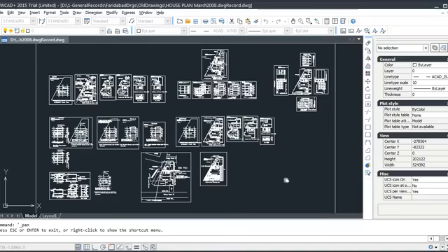Then we have to measure this on site actually, how to measure, how to check what work has been done. I have told you, we have to check everything on site. We have to check excavation, setting out, and then we have to check excavation levels, and then compaction is very important. As I said, compaction means pack as much as possible, increase unit density of your fill or site soil improvement. You have to make it as much air out if possible, and water out if possible, as much as you can expel out of your fill.